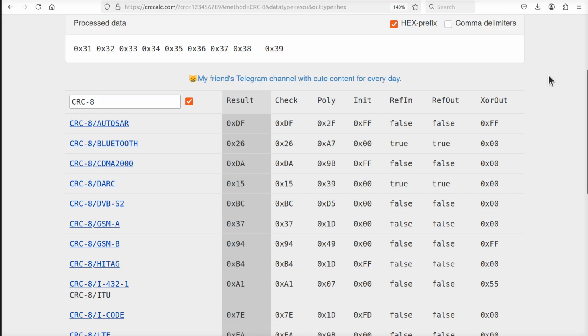So it turns out it would be very nice, if you're going to calculate the CRC while the data is arriving out of an asynchronous UART that sends the least significant bit first, to have a CRC that accepts the data in the native order as it arrives.